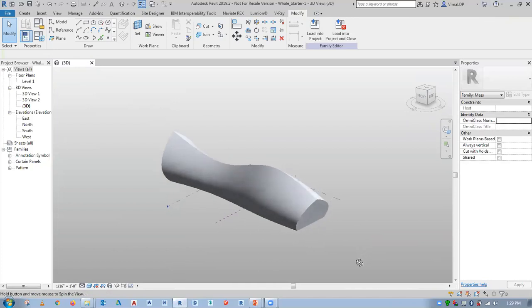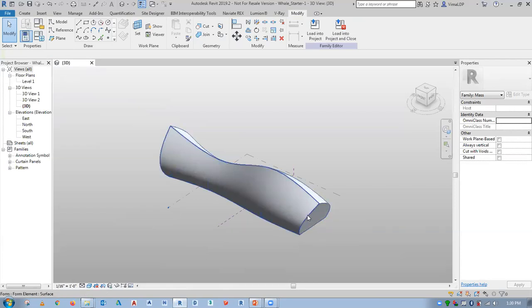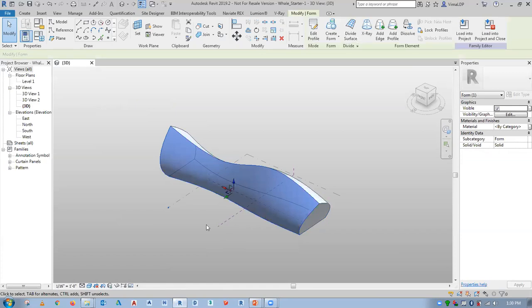So once you have a conceptual mass, profile or the mass element is created, maybe I can edit the surfaces directly here, and I can take them and use them in my project. So for example, if I want this entire surface or this part of my building to be completely glazed, instead of doing that in my project, I'm going to define the glazing or the sizes, the profiles, everything here in the massing itself. So here you have an option of divide surface.